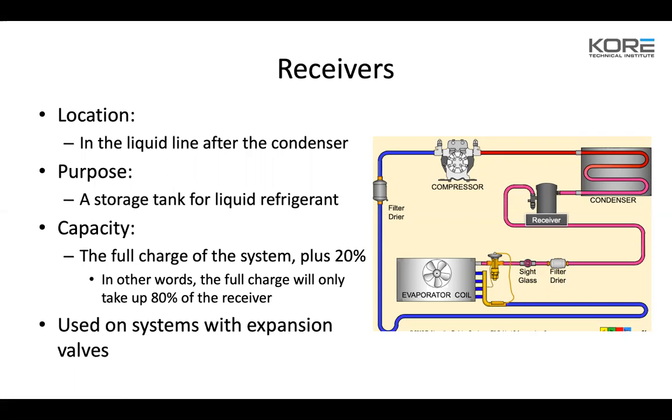So just understand, it's okay to add gas today. Just be real thoughtful about how you're doing that, because we can very much add too much and then we're taking it out in the summer. But we will be stacking gas for the next few days. We usually have our busiest day when we hit our teens and our single digit cold snaps. We're usually out adding gas on the refrigeration side because we don't have enough to stack in the condenser to eliminate that capacity and keep our head pressure up. Does that make sense?